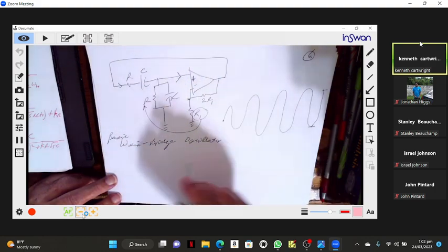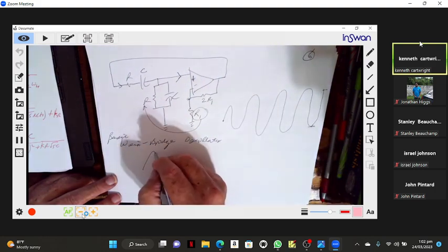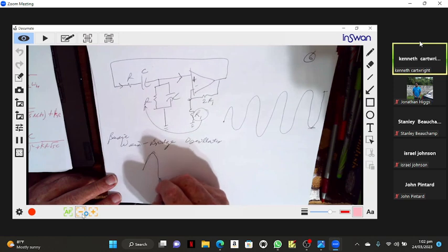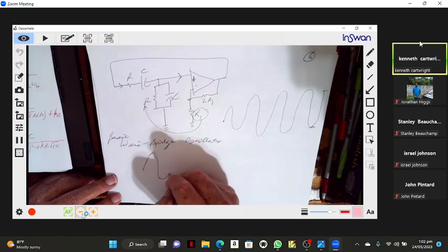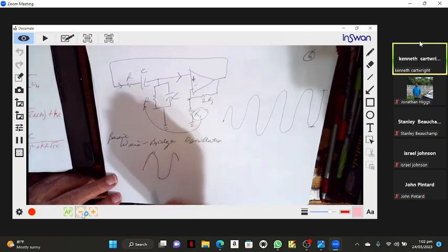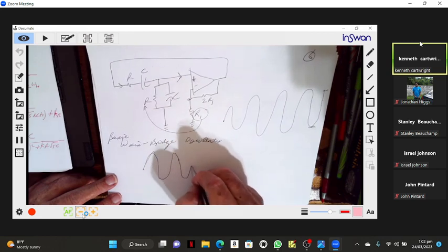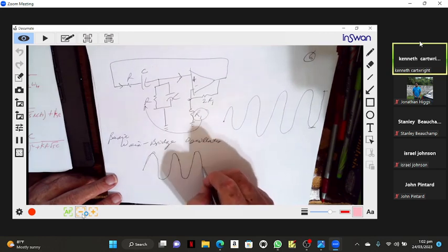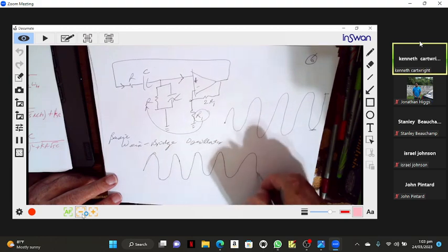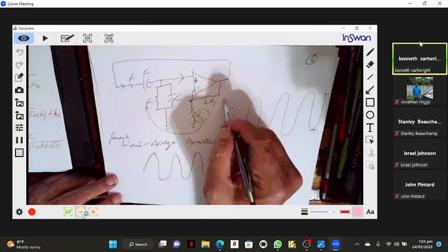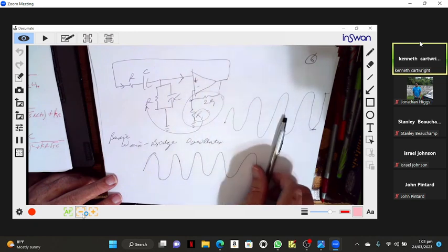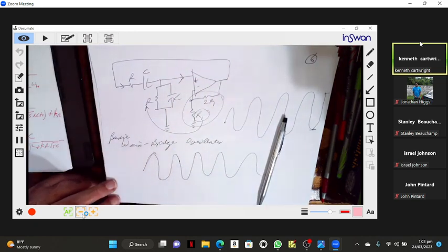The amplitude will go slightly beyond what you get with a gain of 3. When you decrease it, the sine wave decreases a little bit, and then when the sine wave decreases, you have a gain over 3 and the sine wave increases. So overall the sine wave looks like this, but the gain is changing as the waveform changes.